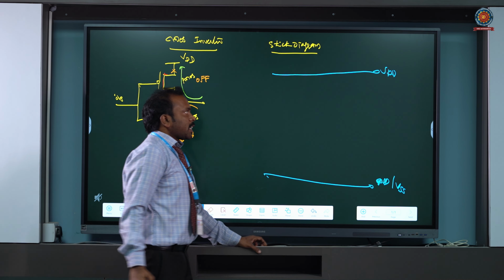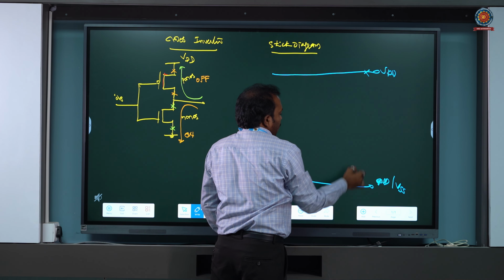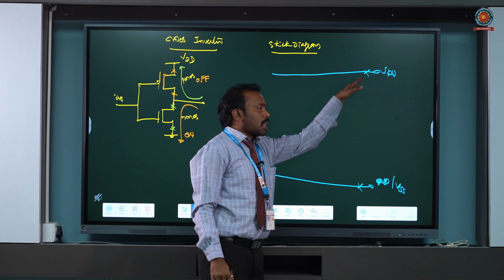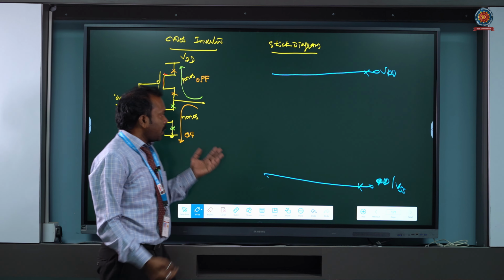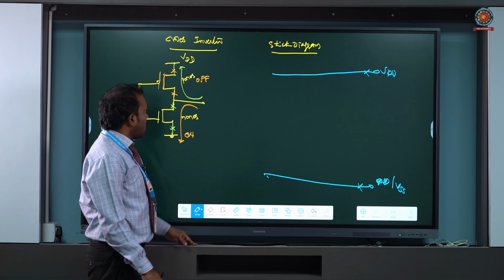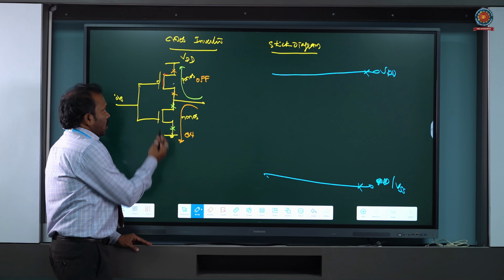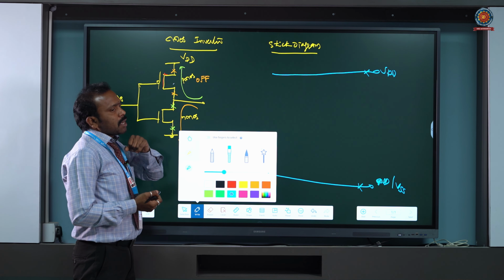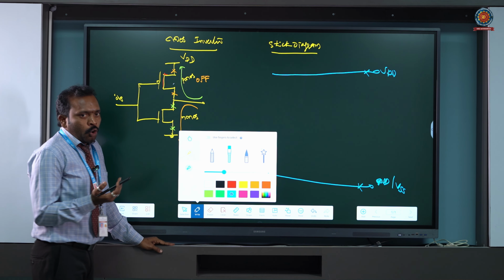Now a cross mark is made on VDD as well as ground, to indicate that these are the power and ground rails which are connecting the PMOS transistor as well as the NMOS transistor. Here, the PMOS can be formed by red over yellow, or yellow over red.